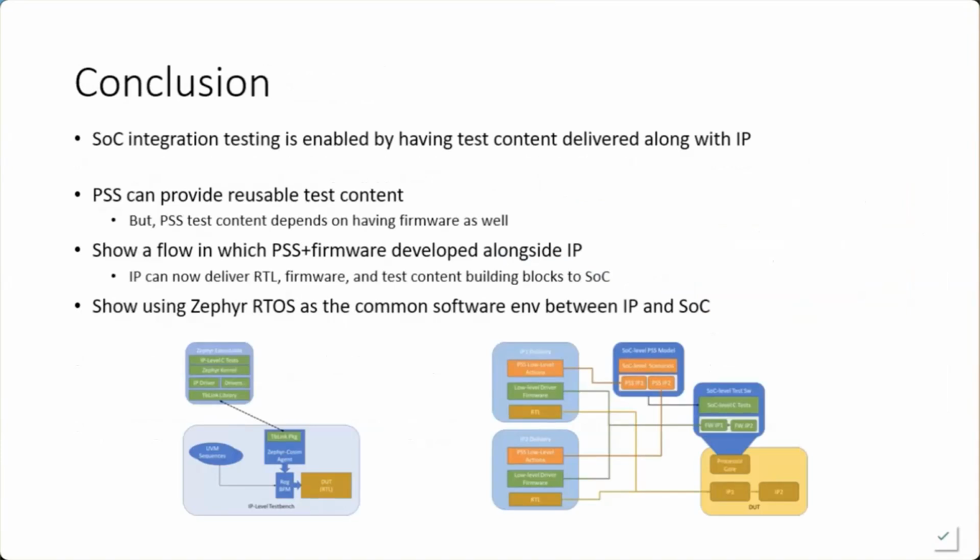So in this paper, we've taken a look at the task of IP and SOC verification and how we can enable tests at the SOC level to be created much more efficiently using PSS. And a key requirement of that is that we have lower level driver firmware available to be used by the PSS actions.